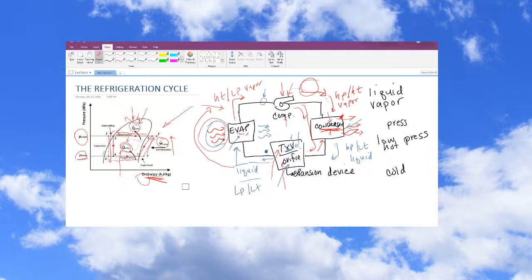Yeah, well, it often is for sure. But on the Subaru, it's often mechanical too. So I have to look at, well, the book will say, check this, check the oil, check whatever, and the book almost always assumes that the check engine light condition actually exists. If it says that it's over advanced, that's because it is. They rarely ever have a situation where it says, well, verify that it's actually advanced. Do this procedure and see if the signal responds as it should.